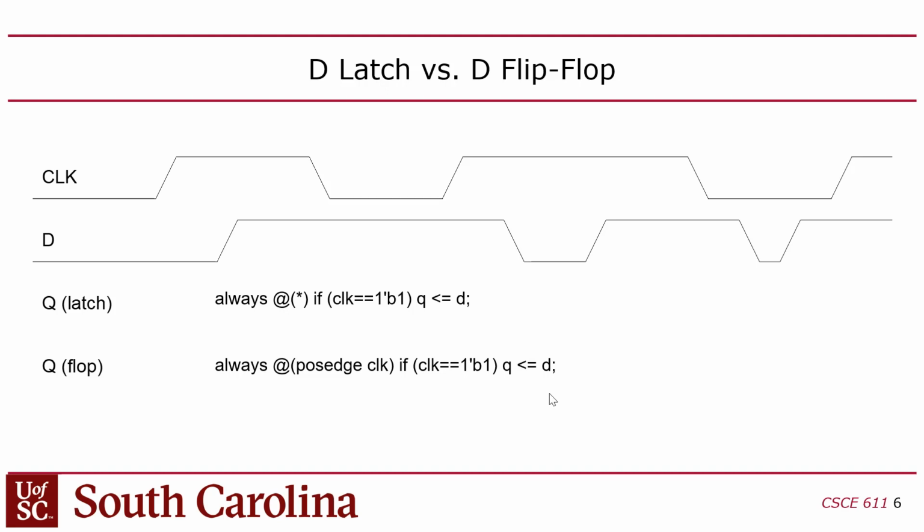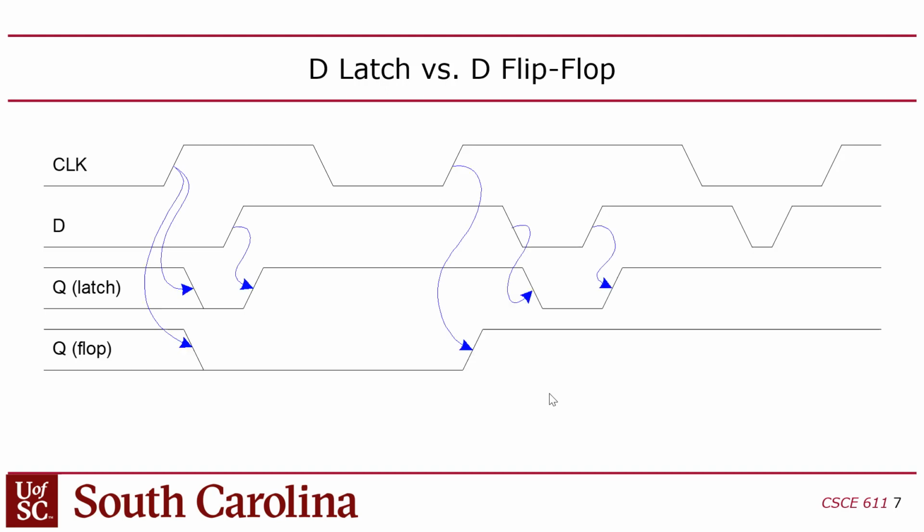If I have code like this and I want to avoid that latch, all I have to do is put an else here, and problem solved. If I put an else on this if statement, I don't have a latch anymore. You just have to ensure that all the outputs get assigned no matter what control path is taken through the always block. You guys with me? Or you could assign Q before this if statement to some default value and then have it redefined in the if statement if needed. Okay?